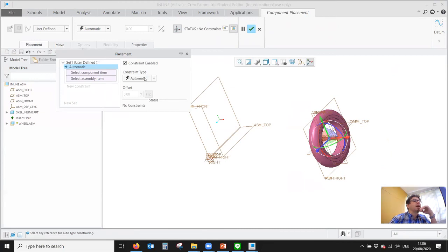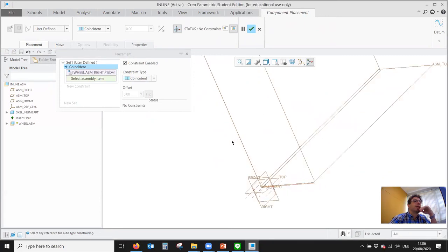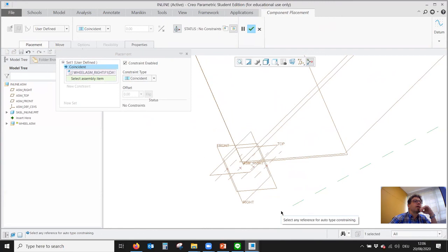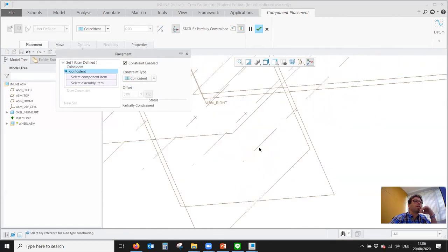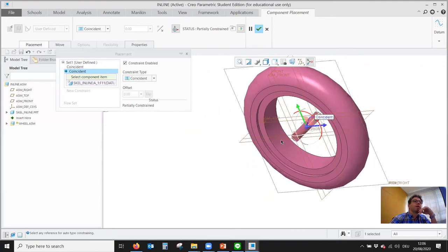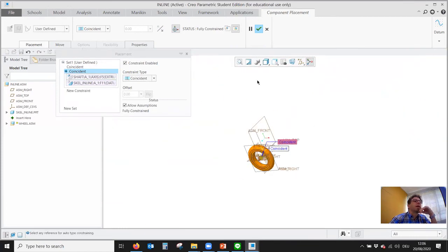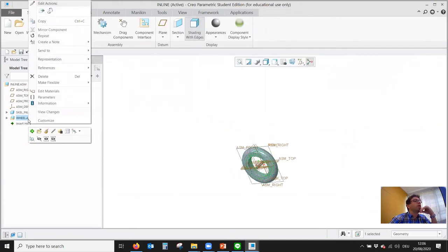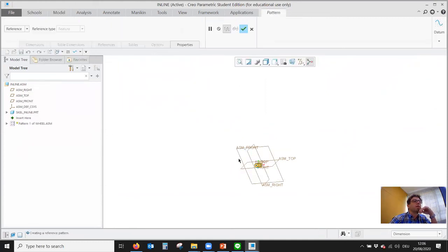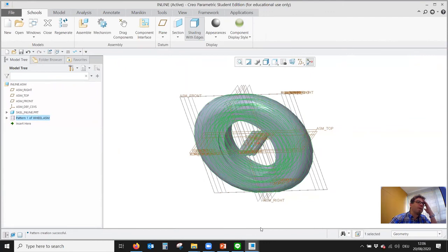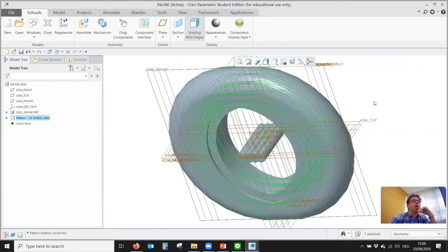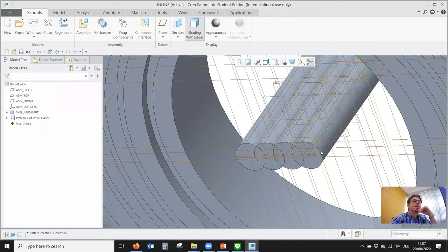Anyhow, so I will place that. I want to have the center plane. Interesting. I don't quite get it. In that center plane, I will make the first axis of the pattern. I hope this is this one. Coincide with this one. Now I can pattern that already, but it will look a bit wrong. 4 points here. Very big wheels, right? So it seems the unit system in these parts is wrong. No problem, just change it.